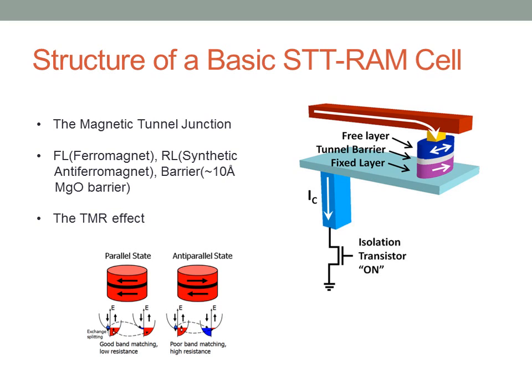To understand STT, we first need to understand the TMR effect. Now, the TMR effect states that when two layers share the same magnetic orientation, then majority electrons tunnel through the barrier, thus giving a high conductance and a low resistance. This is depicted by a logic 0 when storing data. Conversely, when the two layers are not magnetically aligned, then only a small portion of electrons tunnel through, thus giving a low conductance and a high resistance. This is depicted by logic 1 when storing data.